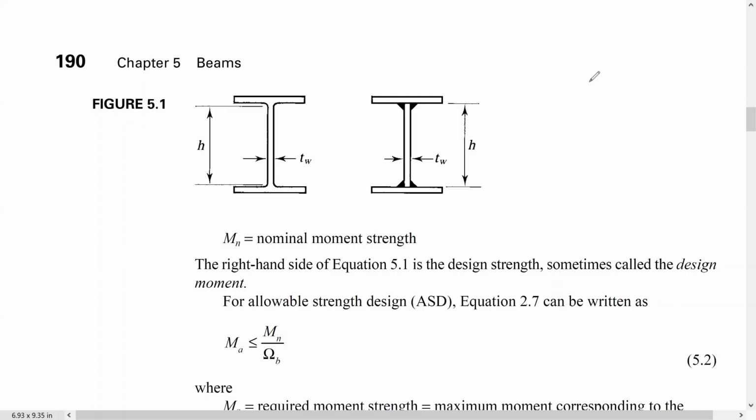As promised, these two figures are wide flange cross sections. But this one is a hot rolled cross section, which is the standard shape. So you see there is no welding, and this is H, this is the web thickness, same here. But this one, guys, is a built up section. So these are plates, look at this, okay? These are plates here, welded here.